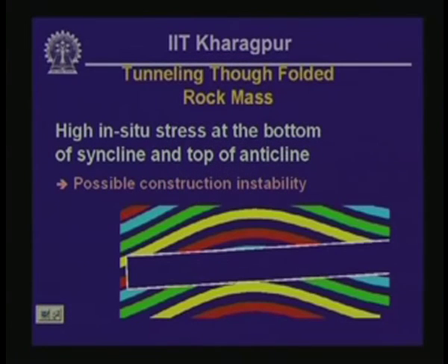Now, what is going to happen? Let us say you have a tunnel being constructed through a fold of the type shown at the bottom right of this slide. If you recall your previous lessons, this type of fold is in fact an anticline. Here, in this particular case, you are going to get a much larger stress near the crowns of these folded layers.